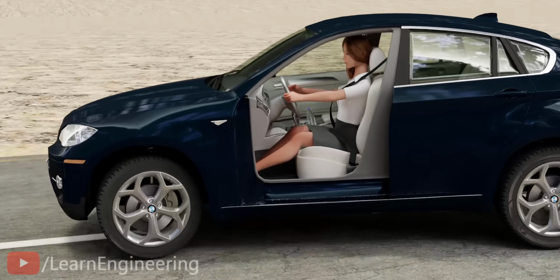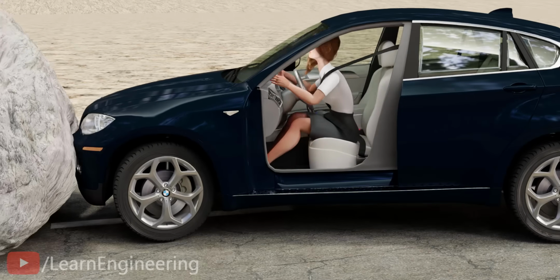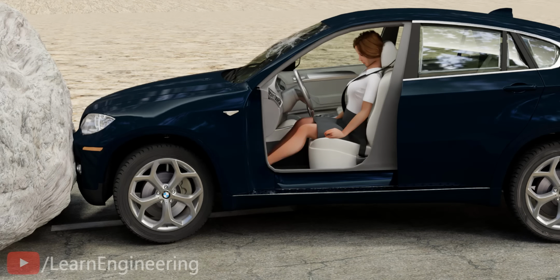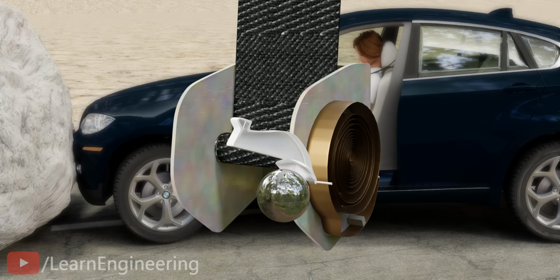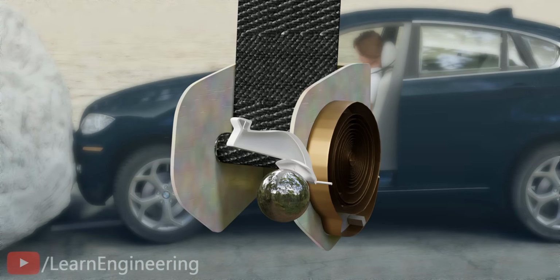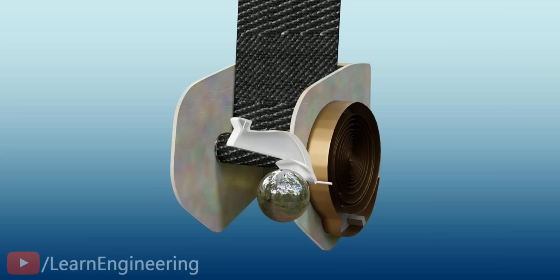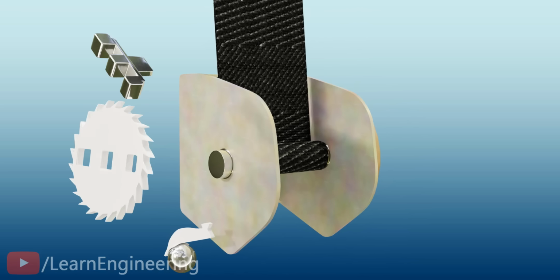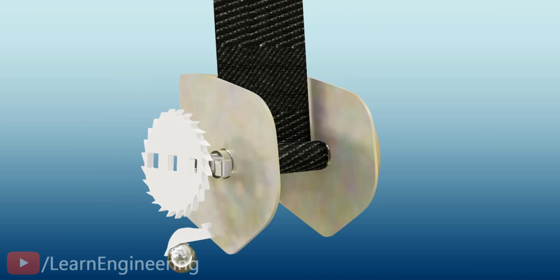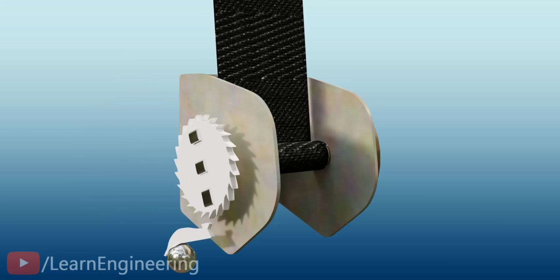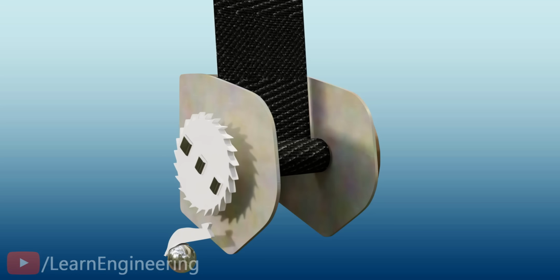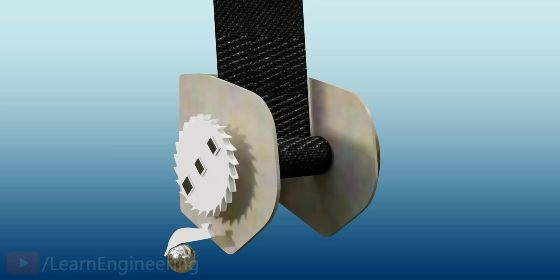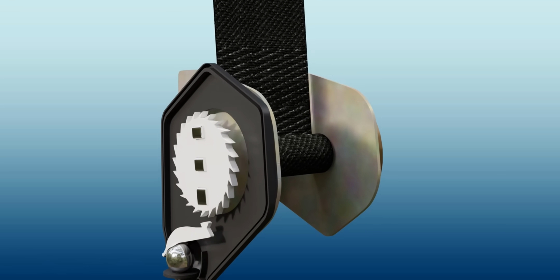During an accident, the vehicle experiences a huge deceleration or suddenly comes to a halt. A clever mechanism can be designed by making use of this effect, using this free-to-roll steel ball and a hinge. The ball is placed at the other side of the retractor, and a sprocket is connected to the retractor shaft. This means that whenever the belt winds or unwinds, the sprocket will spin. Under normal driving conditions, the ball is in a resting position, as shown.